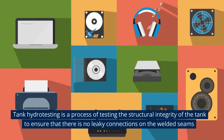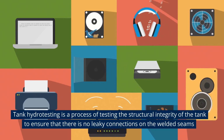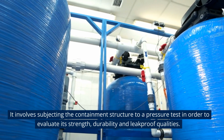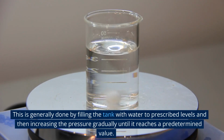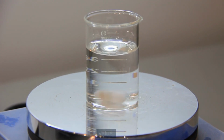Tank hydrotesting is a process of testing the structural integrity of the tank to ensure that there are no leaky connections on the welded seams. It involves subjecting the containment structure to a pressure test in order to evaluate its strength, durability, and leak-proof qualities. This is generally done by filling the tank with water to prescribed levels and then increasing the pressure gradually until it reaches a predetermined value.